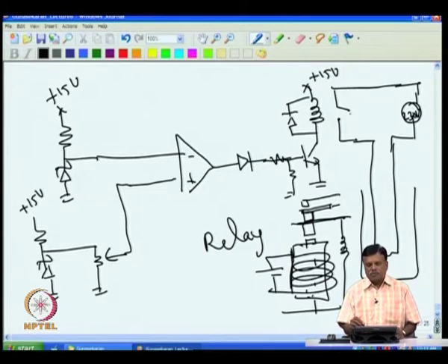So, relays specify the number of on-off operations that you can carry out. For example, there are relays which can withstand 1 lakh operations. If it is specified as 1 million operations, after 10 lakh times the contact goes off, and even when current flows through this, it may not make proper contact and the current may not flow fully. So, this problem will be there in the relay.